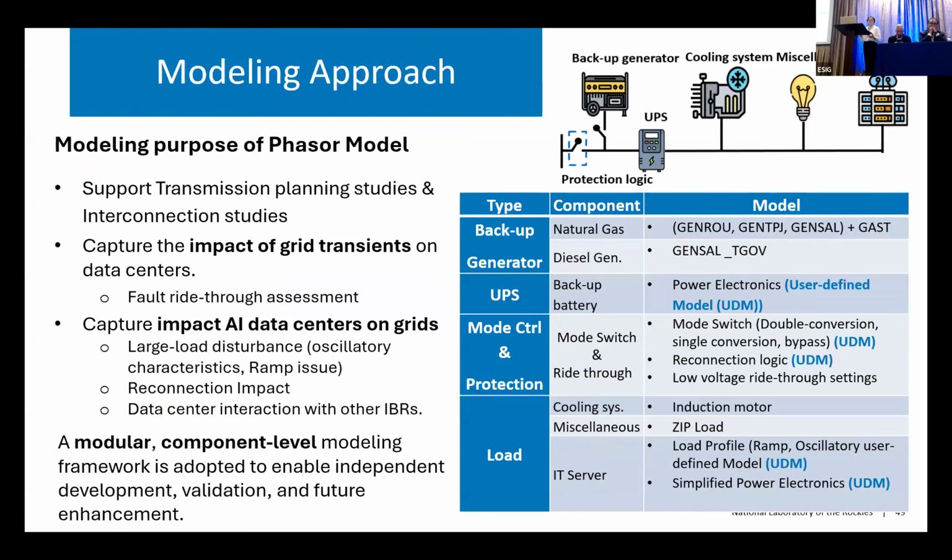Then we come to the modeling approach. For the Phasor model, it's very clear that the model needs to be developed to support these transmission planning studies and the interconnection studies. The key purpose for this model has two folds. One is we try to use it to capture the impact of the grid transient on the data center part. Which means we want to know when we have a fault in the grid, how this data center will perform. First, will it disconnect or still maintain connection? If it still maintains connection, how much support will it provide during the transient?